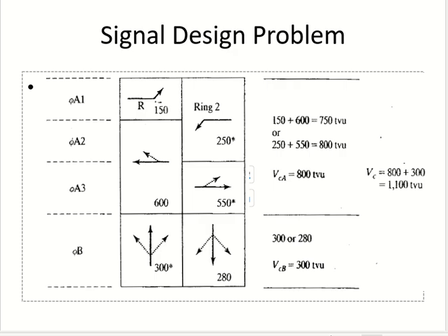Then at the end of A1, at least one of them is stopped. So the next phase has started. You cannot stop or start a movement in the middle of a phase. Whenever you start or stop any new movement, it's the end of one phase and you go to the next phase.